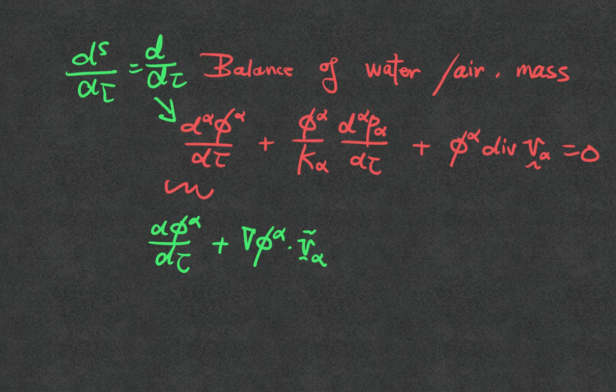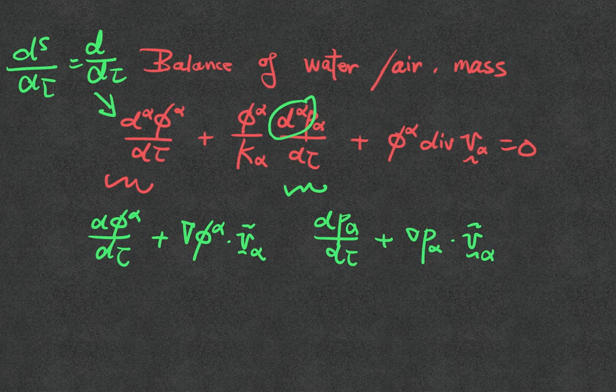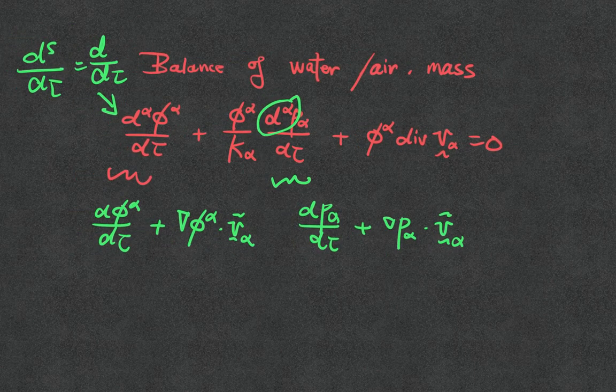Now the second term here, again because of that time derivative, we actually need to switch that to the solid perspective, and that also gives us another convection term. You can kind of see mathematically what I mean by the convection term. There's a gradient of P dot the Darcy's velocity. That gives us the sense of taking account of the change of the P while the liquid is actually moving.